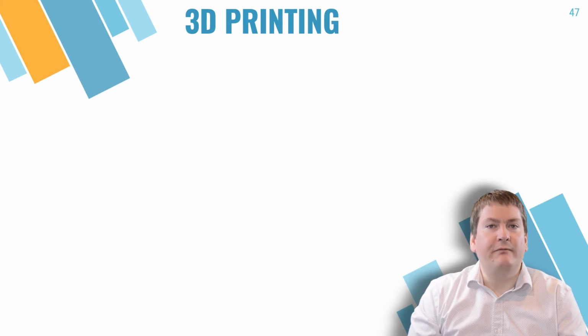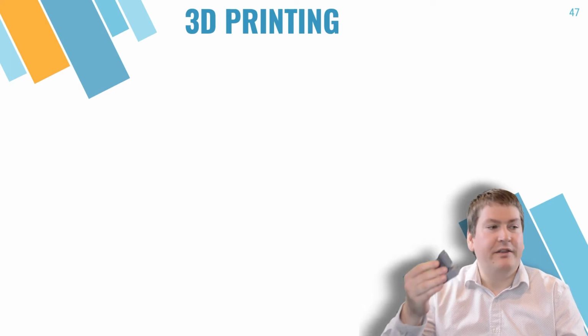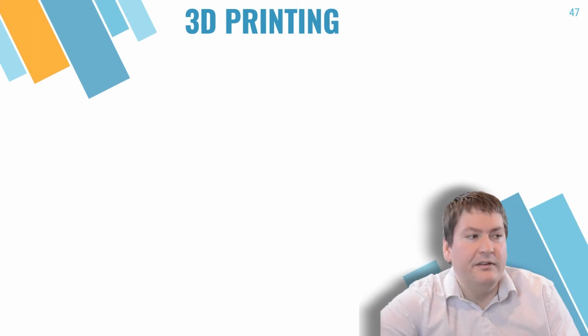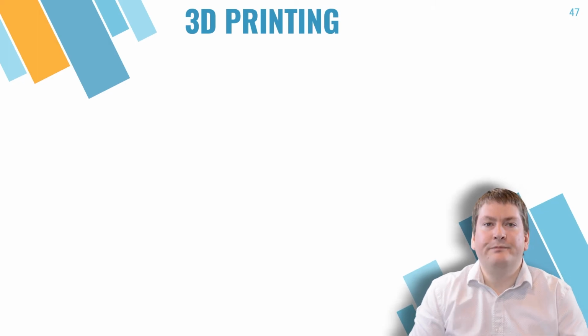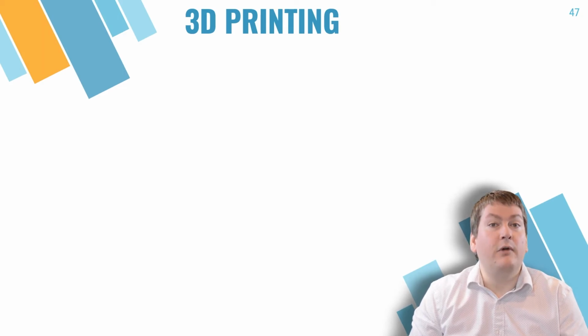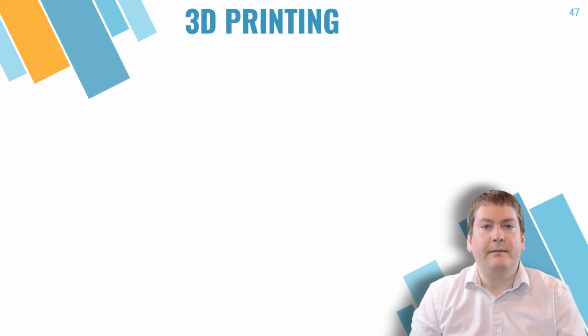3D printing is great for one-off jobs, but it's not feasible for mass production. 3D printers tend to be slow. For example, to print this one little computer here that we saw printed earlier with CS1032 on it, that took about 7 hours on my own printer, and it only made one of them. They also cost a lot more than injection molding in terms of raw materials, maintenance, and electricity. The strength of the parts they create is also weaker in most cases than those created with a conventional mold.